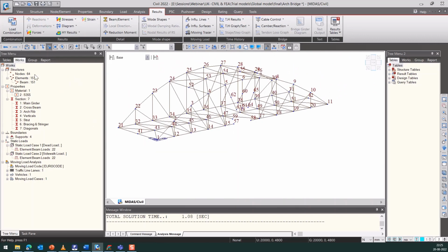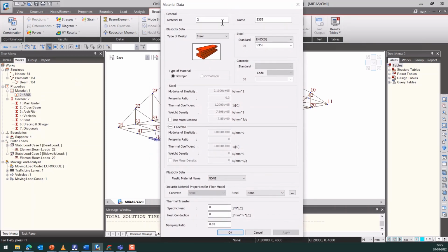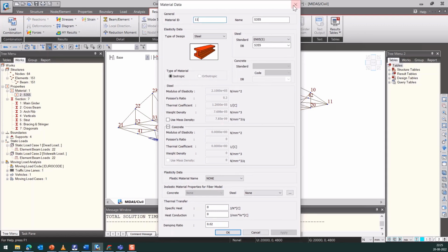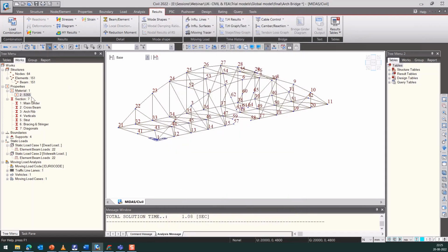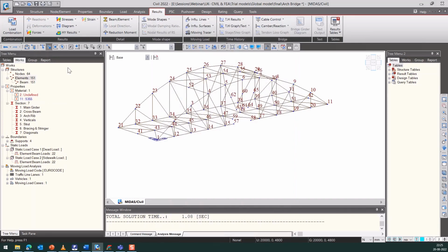Now, since we have defined a material number and material properties over there, we'll be updating this particular material number. We'll start it from 11 so that the materials coming from FEA NX do not overlap with this. Okay, so let's do that. Let's start with 11. Okay, and we'll assign this material to everything. So our material property starts at 11.